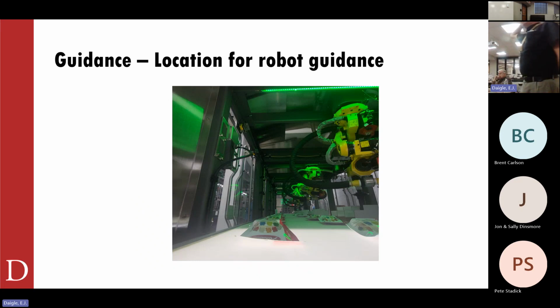This is the one I was going to show you. This is the line that my son did. Now this one's a little different too, in that you'll see that this conveyor belt has some lighting from below as well. Sometimes you'll see what we call dark field lighting, bright field lighting, or backlighting. Those are the three main types of lighting systems you're going to see in machine vision. So with backlighting, the part is sitting on a conveyor belt and I'm going to light up from underneath, so my part's going to look like a black blob. This is a technical term, and you're going to think it's not, but it is. In machine vision, one of the most impressive technical terms is a blob. That is the term that everybody likes to use.